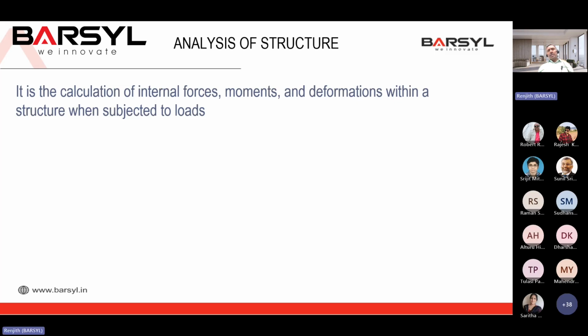The bottom slab has two components, toe side and heel side. The earth side of the bottom raft is called the heel side, and the other side is called the toe side. Maximum base pressure will come at the toe, at the bottom. So the tension reinforcement will bend up, and hence the reinforcement is at the bottom, on the tension side of the toe slab. For the heel slab, it will usually be at the top of the base slab, and the detailing will be done accordingly, and minimum reinforcement will also be there.